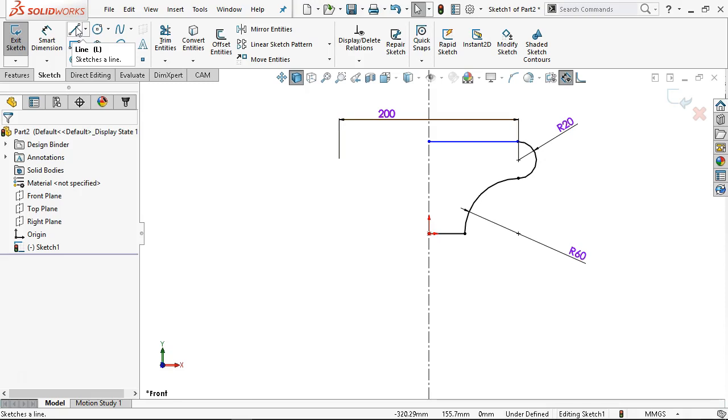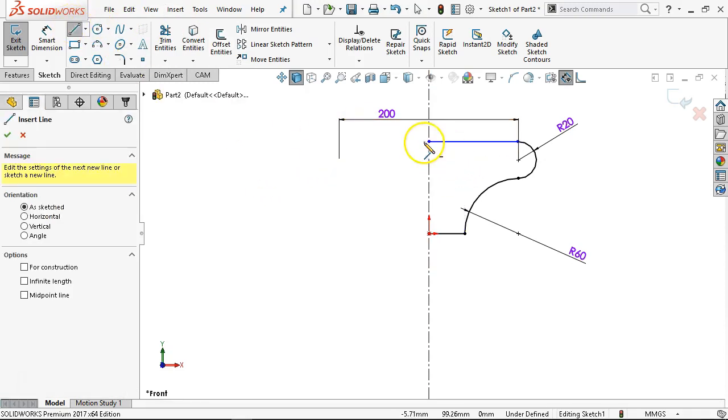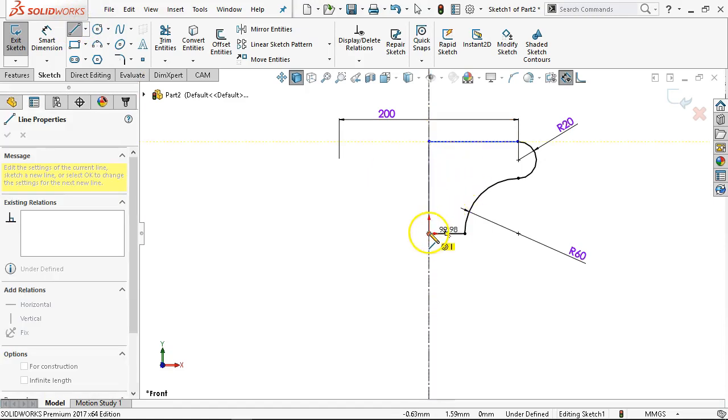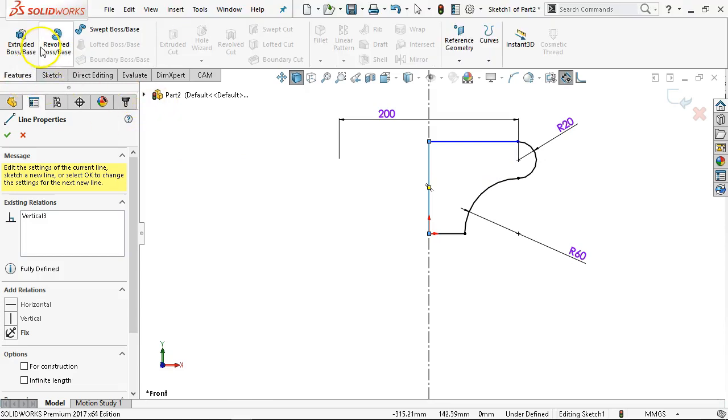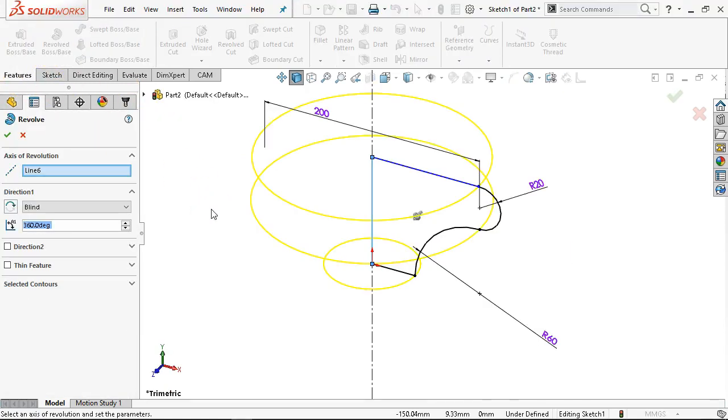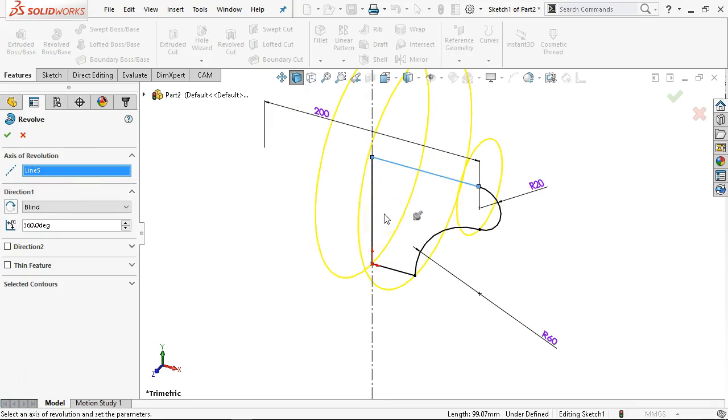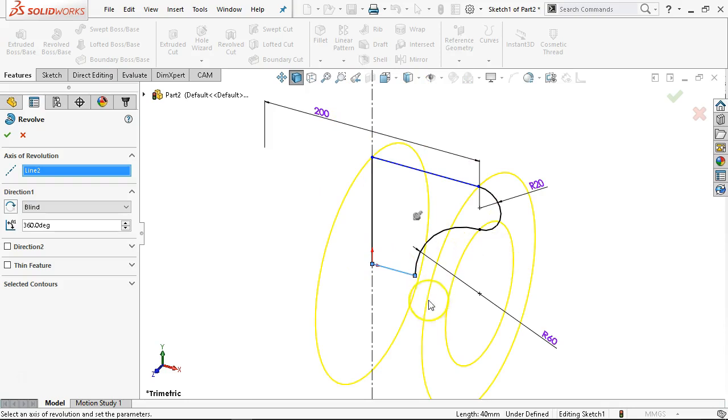are we going to make a boss extrude or a boss revolve? To make this a boss revolve, I need to close it off. If I don't close it off, it will ask me, but it still wants a contour region. It wants an enclosed space. And the difference is that when I go to revolve, it's going to revolve around that center line as a default. I can pick any geometry that does not produce self-intersecting. Revolves about that line. It's going to make a little bubble, looking kind of weird, but whatever. Or the other way, a little dish.